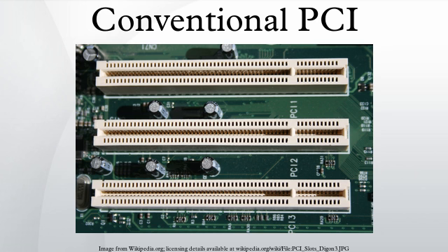Auto-configuration. PCI provides separate memory and I/O port address spaces for the x86 processor family, 64 and 32 bits, respectively. Addresses in these address spaces are assigned by software. A third address space, called the PCI Configuration Space, which uses a fixed addressing scheme, allows software to determine the amount of memory and I/O address space needed by each device.